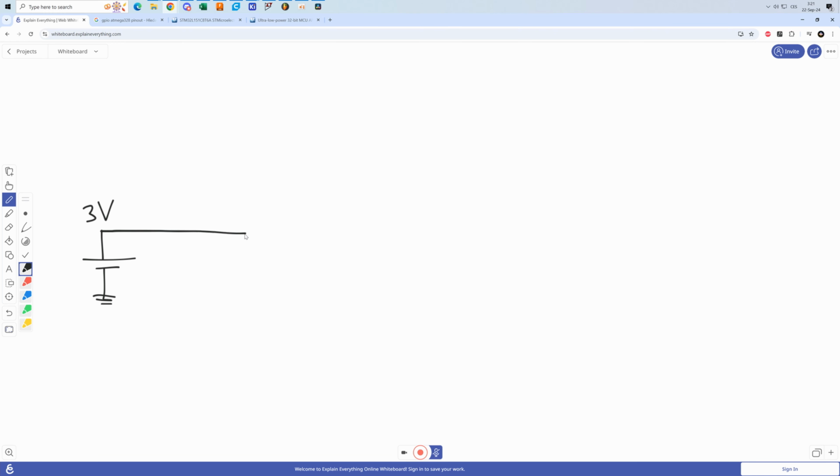And now how do we decide how to convert this voltage to a digital value? Well, we could do such thing that we will have a comparator here, just like so. And we will feed, for example, 2.5 volts over here. This is some voltage reference, some stable voltage reference. We can tell that this is 2.5 volts at all times. Now, the output of this comparator will tell us if the voltage is higher or lower than 2.5 volts.